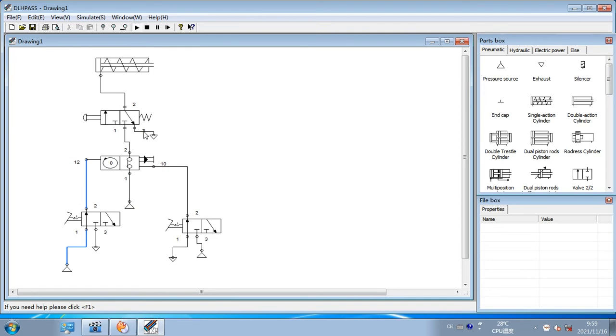At the count of 3, you can see contact is being made, and pressure air goes into the pneumatic DCV. When you press this button right here, you can see it extends and it retracts, and then you release. When you press this, it resets. So right here, this is the operation of the pneumatic counter. All you have to do is just drag and paste, and then we move into the next operation, which is a sequence operation.